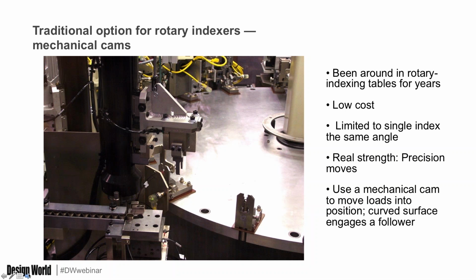Shown here is a really beautiful example from Cavalry Automation. Cavalry Automation is based near Rochester, New York. This is a high-tech integrator that sells synchronous and high-speed assembly platforms with integrated cam motion, pick-and-place, or probe units, mostly up a common drive shaft. The particular offering from Cavalry uses rotary indexer subsystems from companies including Camco, Stelron, Cam Driven Systems, and Sankyo.